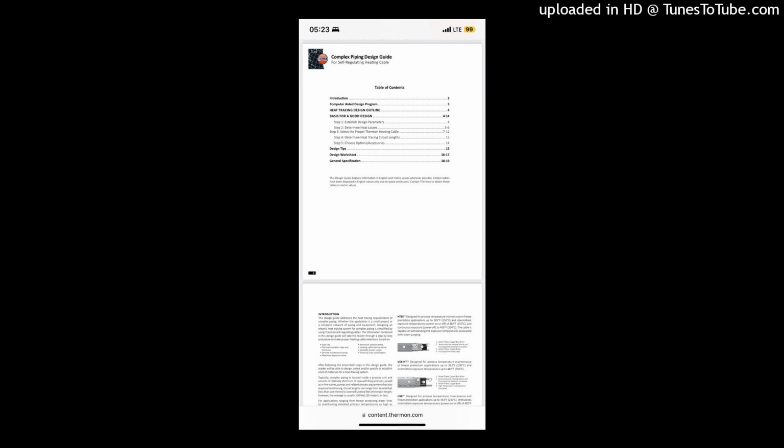Calculations made within the program are based on the formulas prescribed in IEEE Standard 515. The information input to and/or generated from CompuTrace can be printed, and a summary report, including load chart information, exported for use in other programs. While CompuTrace is a valuable asset to use in designing a heat tracing system, the design steps detailed in this guide will still form the basis for identifying the design process necessary to establish a properly functioning heat tracing system. Heat tracing design outline.